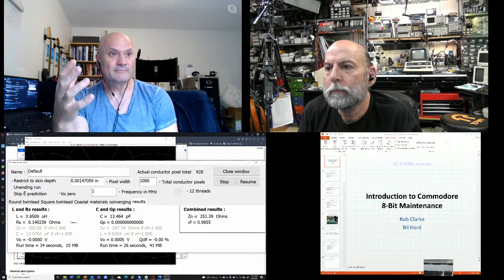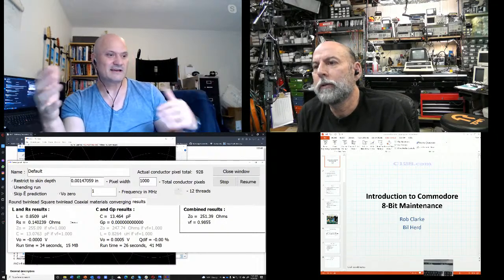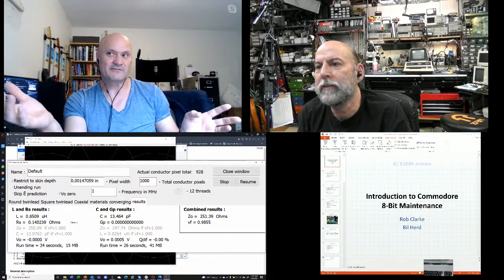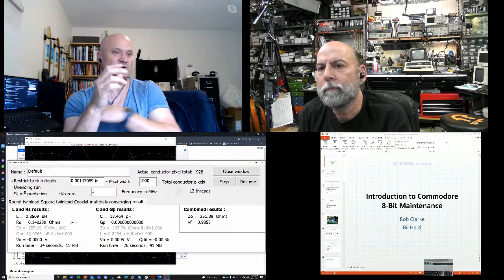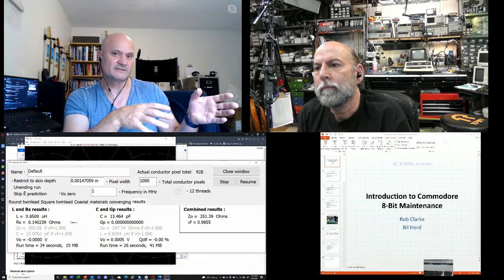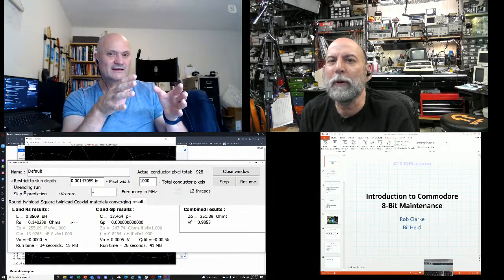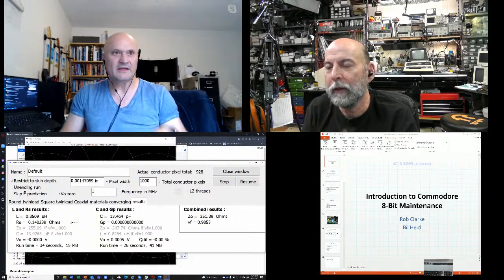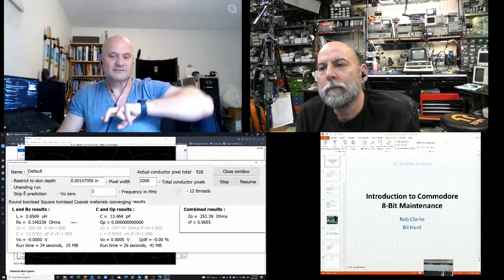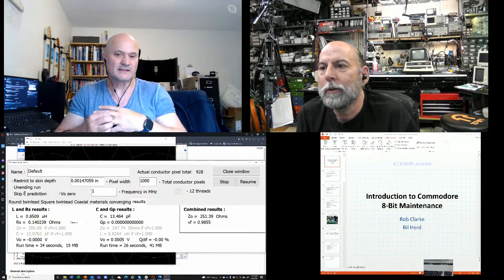The natural impedance of free space and air is almost exactly 377 ohms. And this is why it's awfully convenient to use twin lead that's 300 ohms, because it's very close already. It's a compromise, but it's close. And then you can run from your antenna down to the rig. You can run twin lead at 300, and they're not perfectly matched, but they're close.